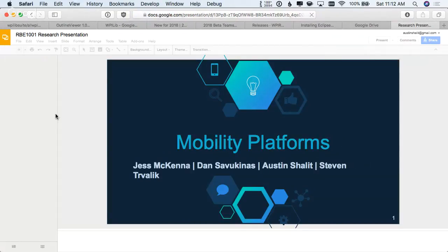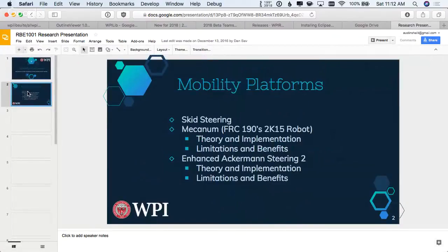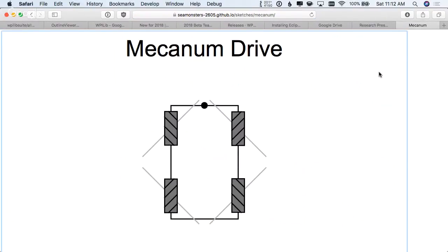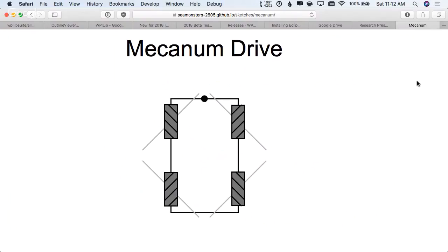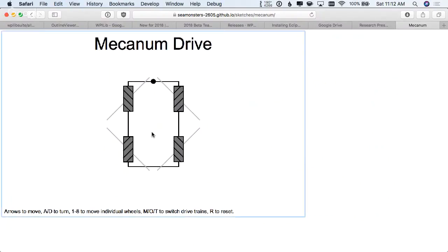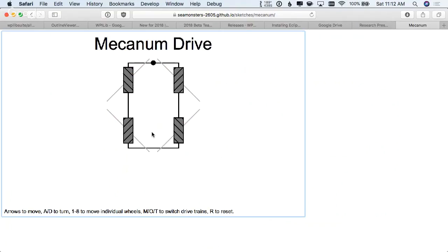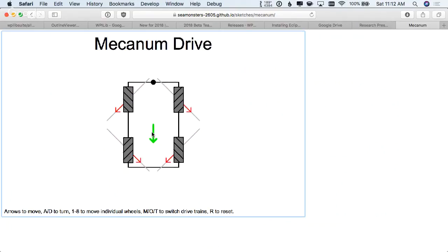So if the robot is just like this, and I'm here, and I push it forward, it will just go this way without changing its orientation. Then you use the rudder control on the joystick to make it rotate. The direction vector comes from which way you move the joystick, and the rotation comes from how you twist the joystick. So you can make it go straight.